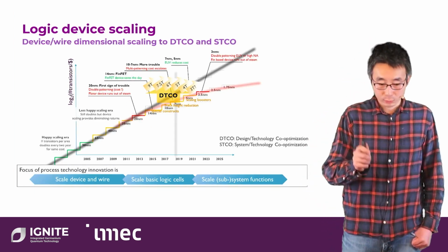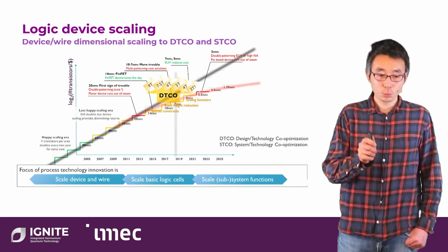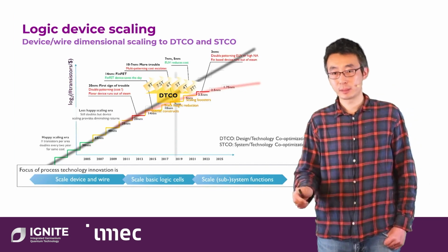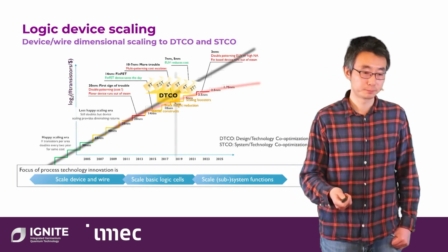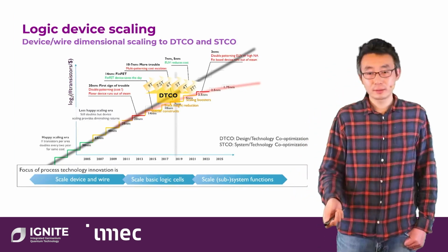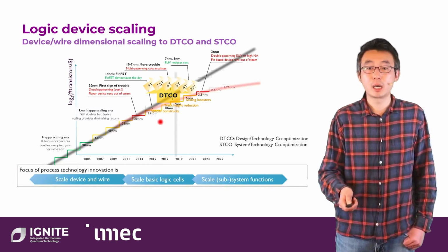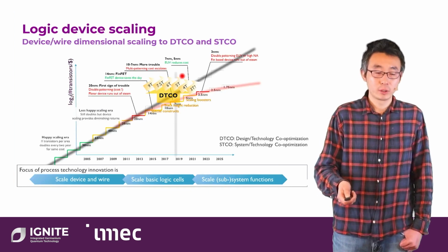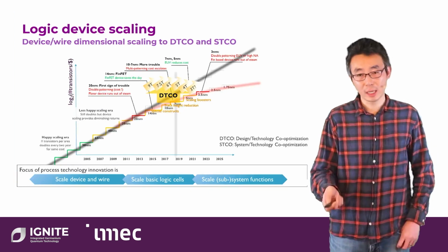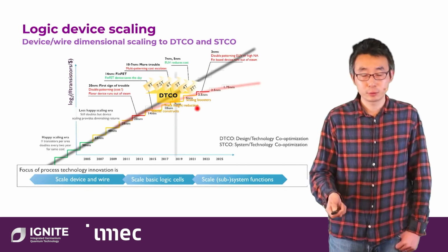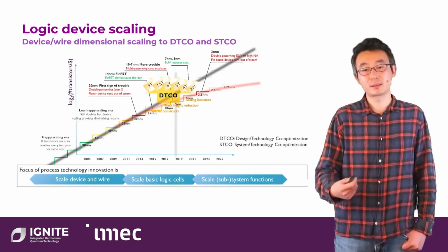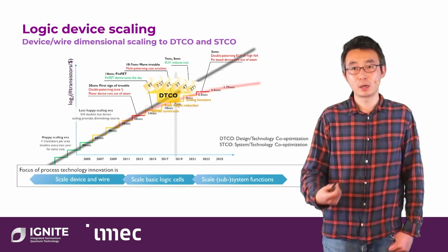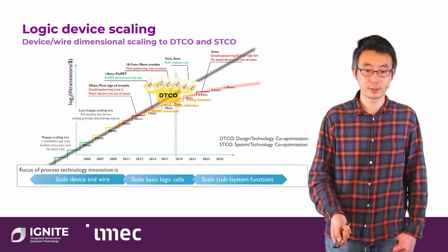However, as I explained earlier, when you have a transistor, it actually incorporates multiple fins, essentially to have high current flow through. But for the downscaling requirement, you also need to reduce the number of fins. Okay, so how can we achieve that? Well, by material optimization and also clever structure design. And for the structure that even goes beyond, we can expect some larger deviation of the real performance. And for that, it's really the gate-all-around structure and more innovations.